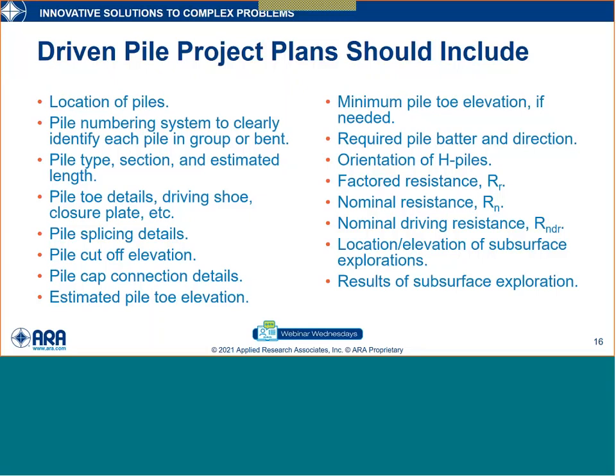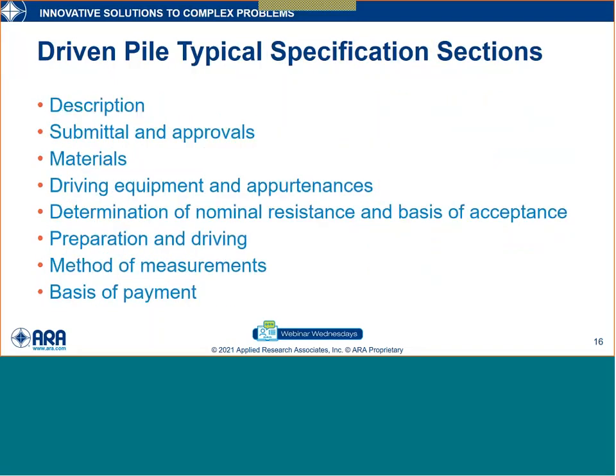It's easy sometimes to have a disagreement between the geotechnical design reports that are finally approved and what's in the plans. And in many cases, in particular on alternative contract delivery projects, the geotechnical reports are part of the contract documents. So conflicts between the geotechnical report and the plans will get you in trouble. You need to check. Make sure all these items as needed to be addressed are included. Again, just an example. Sticking with driven piles, let's focus on specifications.